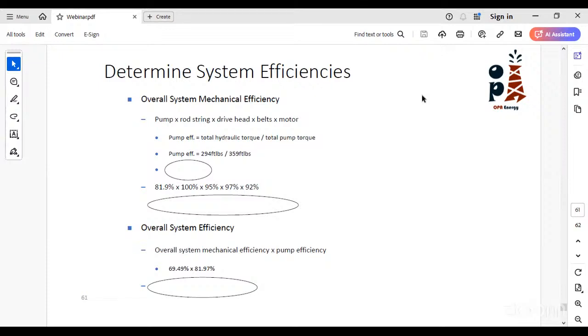One more thing is that you have different gas separators for the PCP system, and of course deploying the VSD system with your PCP and remote controlling for your PCP can give you a lot of advantages.